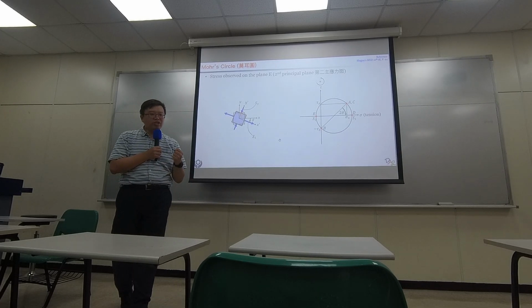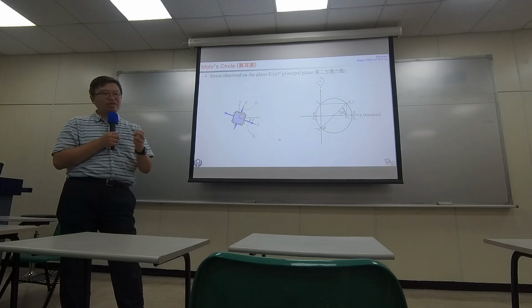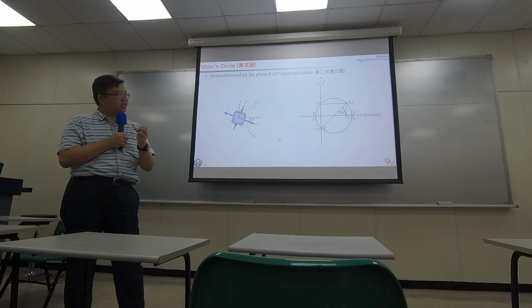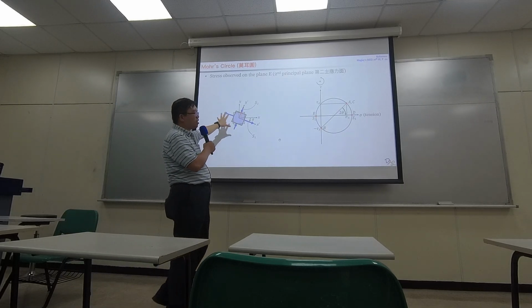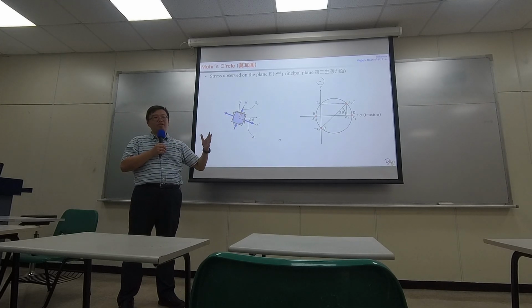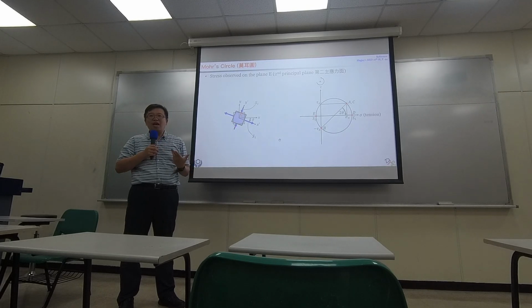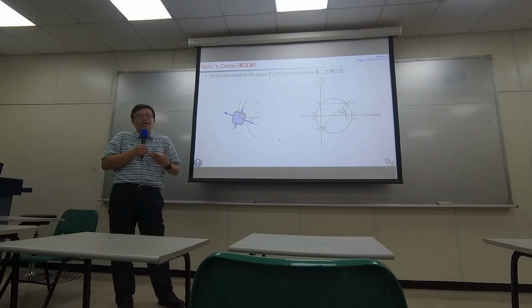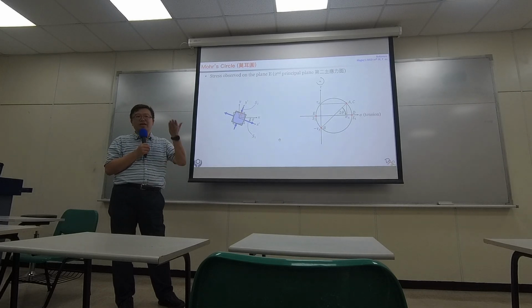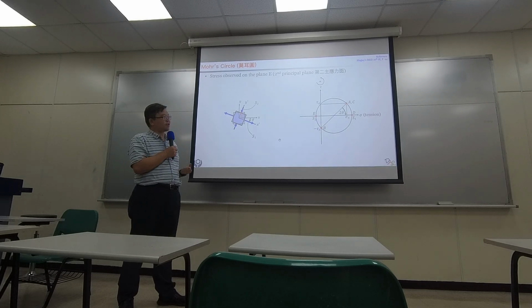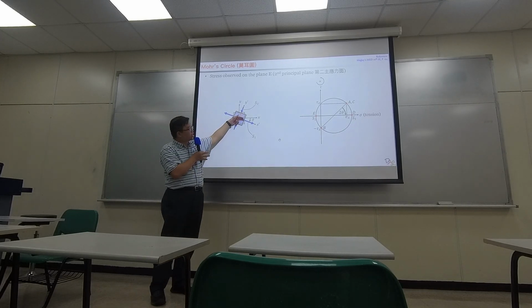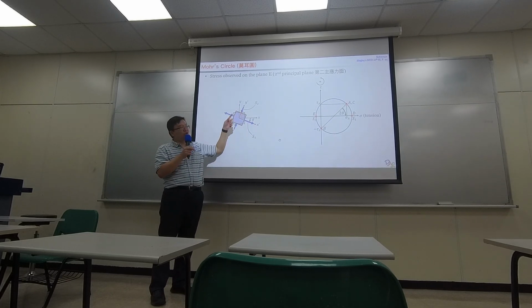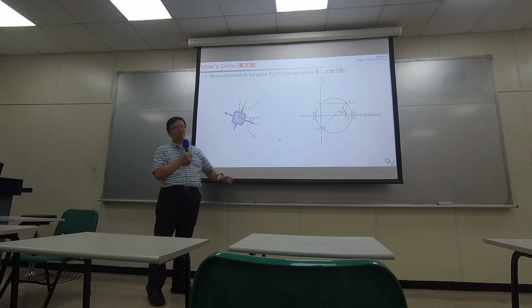Because we need to know how the element is carrying the most load. And we want to check if that largest load is greater than our strength. So if you observe in a different orientation and it's actually telling us it's not carrying this much load, then we will underestimate the load. So basically, we will have a lower design than a safe design, which is not good. That's why we want to use the Mohr circle to find out, basically along this orientation, this element will be carrying this strong load, a tension load in this direction, this amount. So let's worry about this.